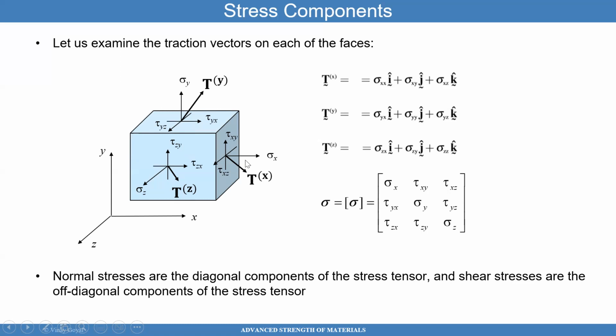And the bottom line there is that this traction can be decomposed into these three directions, and these are the stress components. They're acting in that phase. The sigma xx is called the normal stress, and the ones tangential to that surface are called the shear stresses. So these two shear stresses are tangential to that surface whose normal is in the X direction.